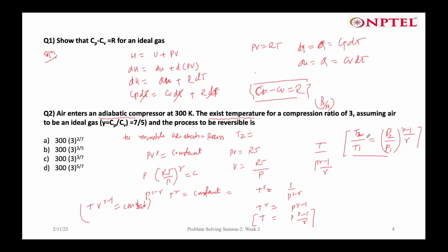Now put the value here: T2 is equal to T1 (P2 by P1) to the power (gamma minus 1) divided by gamma. So here T1 is 300, compression ratio 3, and gamma 7 by 5, divided by 7 by 5, right? So 2 by 5 means...